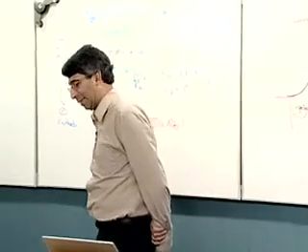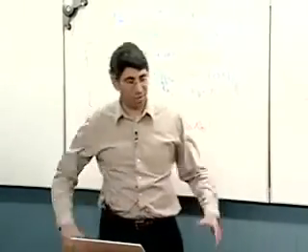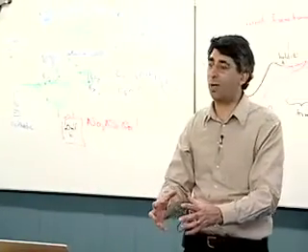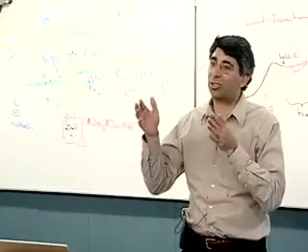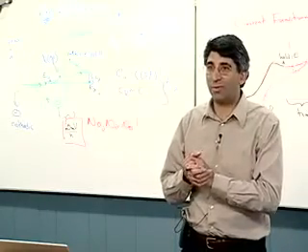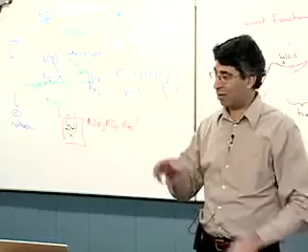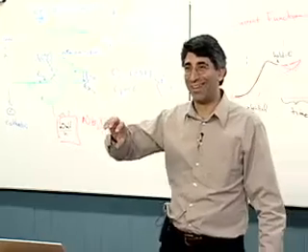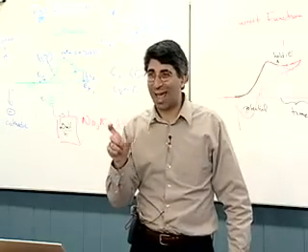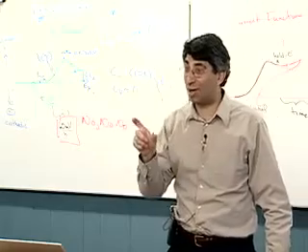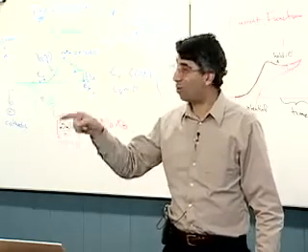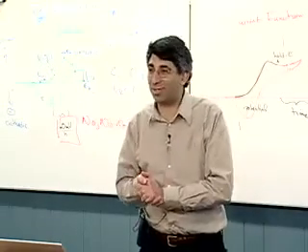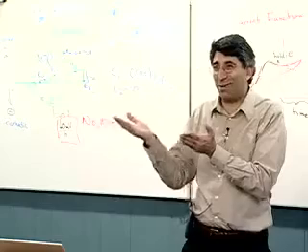If you decide in your electrochemical cell, your cell is close to your, I should point something out. If you use an old 173 potentiostat, it has an external electrometer. And the reason for that is PAR, the real PAR, knew that it was important to have a short distance between the electrometer and the reference electrode, because if you put a long wire in, there would be a resistive loss there that your most sensitive electrometer would say is part of the system.